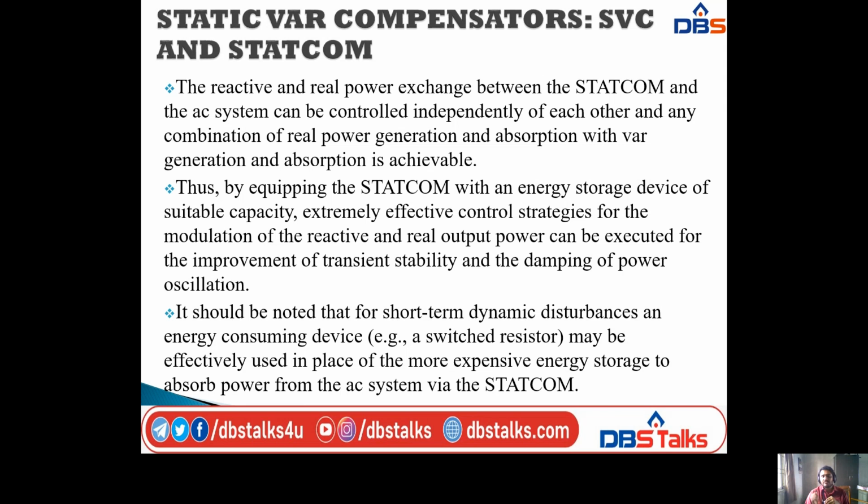So thus, by equipping the STATCOM with an energy storage device of suitable capacity, extremely effective control strategies for the modulation of reactive and real power exchange can be executed for the improvement of transient stability and the damping of power oscillations. It should be noted that for short-term dynamic disturbances, an energy consuming device, that is a switched resistor, may be effectively used in place of the more expensive energy storage to absorb power from the AC system via the STATCOM.